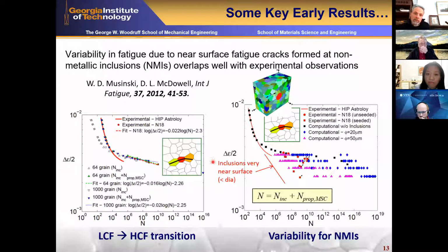So it's crossed that threshold, the first strongest grain boundary threshold. And in this case, we didn't use a rigorous small crack growth law. We just looked at the probability of extending across the grain due to the driving force of the adjacent grain. Later, I'll talk about small crack growth laws in more detail.